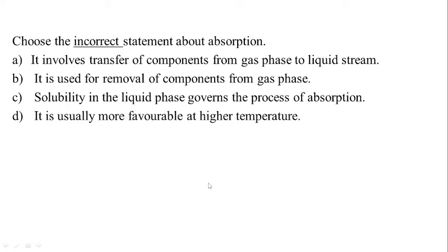In the condenser, which is subcooled, quite likely most of the product entering this condenser as feed is going to be condensed as liquid and finally leave as a subcooled liquid. That means it's a liquid at a temperature below its bubble point.